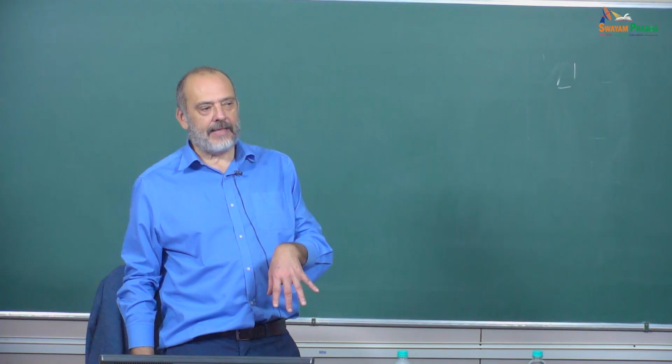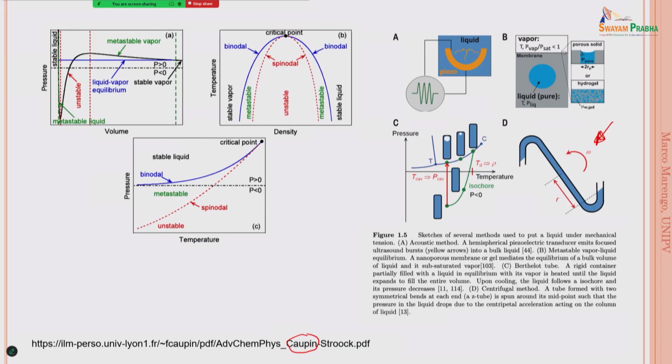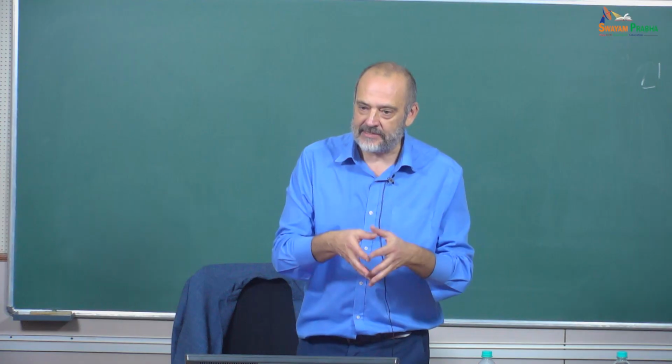And one can ask, why are you saying that? For example, now I'm studying a lot of negative pressure. I'm doing a lot of work on negative pressure. Why? Because when you're dealing, for example, with flash atomization, very rapid processes, you may land in metastable conditions, because you are going from the liquid to the vapor so fast at low temperature that you enter the negative pressure regime. You are stretching the liquid with the flash atomization, for example, of hydrogen and so on. So it can be very interesting, because if you don't consider that, you are not really considering the real physics that is happening there.